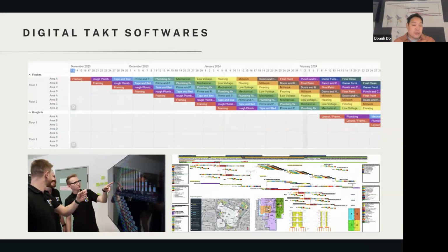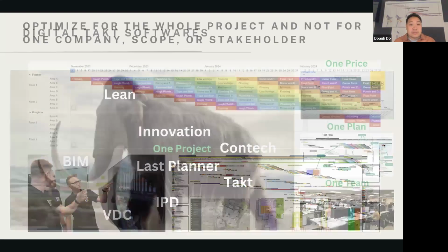And when you're using TAK on your projects, a lot of people label the zones and they have blue tape around the zones so people know which one is which zone. And in between the zones, they label who's working there and also what the conditions of satisfaction are when they're finished. So that makes it super easy to quality control.